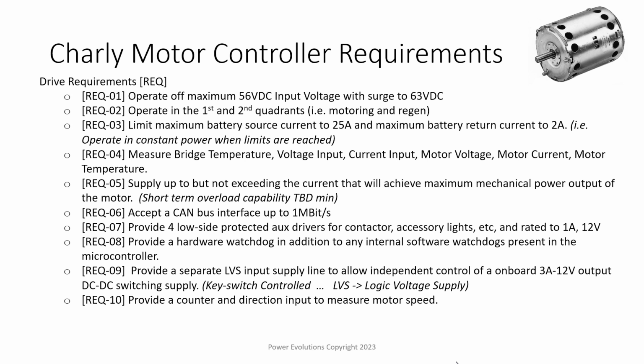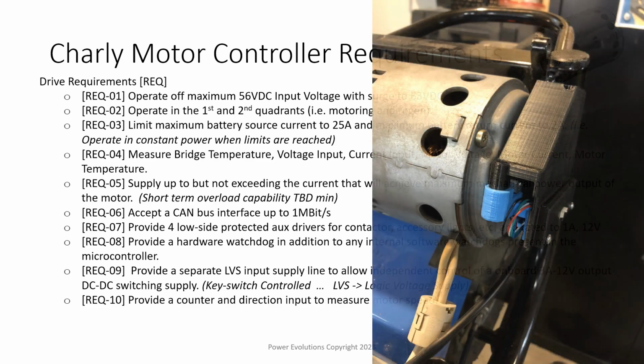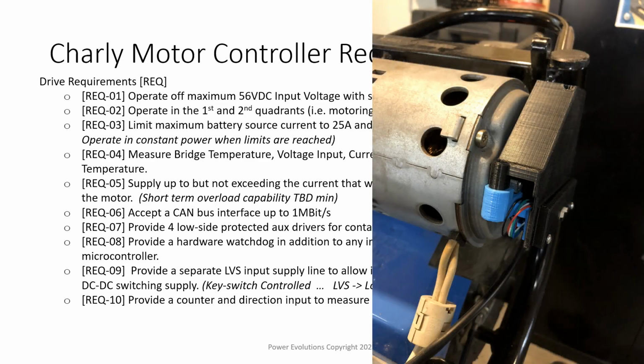The last thing that I'm looking for is a counter input that can take the pulse from my encoder that's on the motor. I've created this and installed it because I want a lot tighter feedback on speed than what I would get from the single pulse per revolution that you get from the front wheel. My hope is that this is good enough to wrap a wheelie popper, or should I say anti-wheelie popper control, into the throttle,